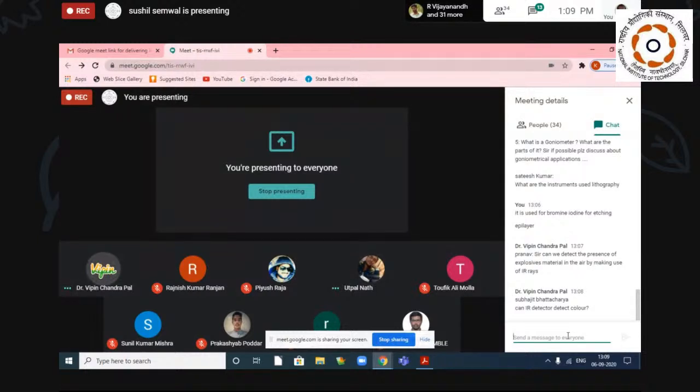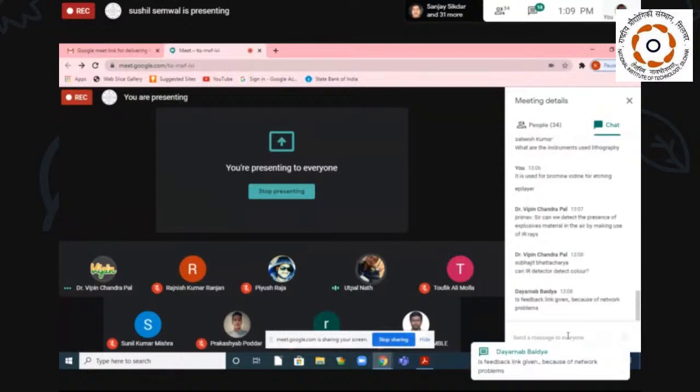Okay, sir. Sir, one participant named Satish Kumar asked what the instruments used for lithography are. That I had already shown in my slides. If we want to do lithography, then we have a spin coater unit, then we have an oven or hot plates for baking the photoresist, and then we have a mask, and then use a mask aligner which is used for exposing the pattern on our photoresist, and then we have to develop it.